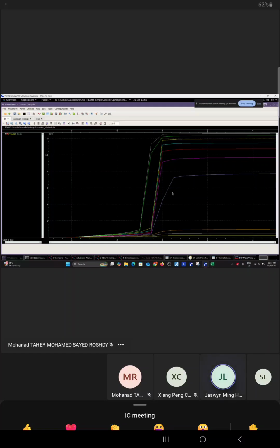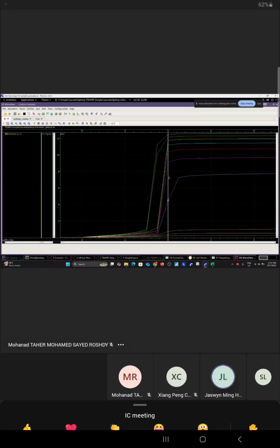So it's 0.5. Can you do the cursor then? Increase the width, the ceiling gets lower. See, from negative 400 to 400, negative 0.5 to 0.5. Then you see that when we increase the width of the bottom MOSFET, the ceiling gets lower.